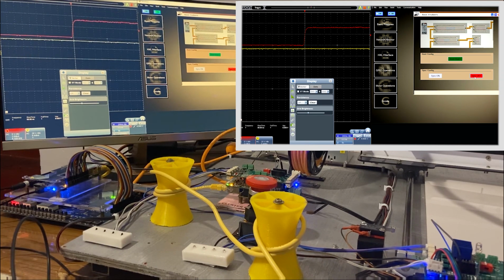When we calculate that value for 255 slaves, we get around 6 microseconds. Now we are going to show the GPIO operations. Under this, we are showing digital read and write operations. Each slave has 8 input and 8 output pins. Here, the first 4 input pins can be configured as interrupt pins.